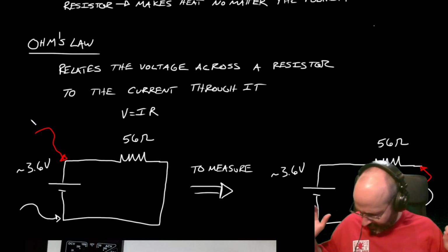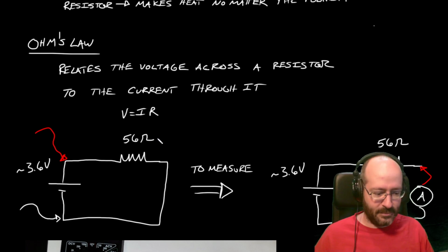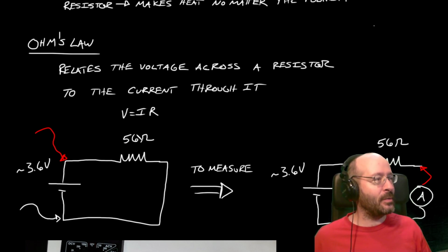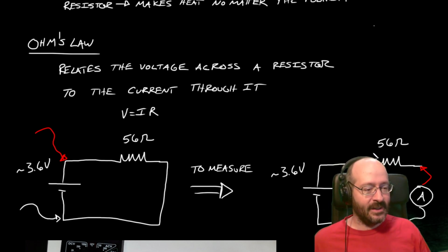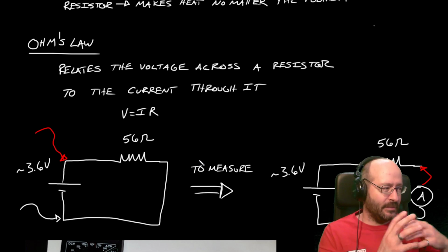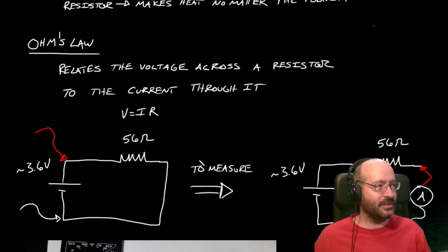Okay, where'd my resistor go? Oh, good thing I have more. Okay, so measure that voltage, 3.7. Yeah, that's about right. Okay, now measuring current, we got to remember that current is a flow rate. So we have to count how much charge is going through. 3.75. These are still pretty well charged. Those are good.